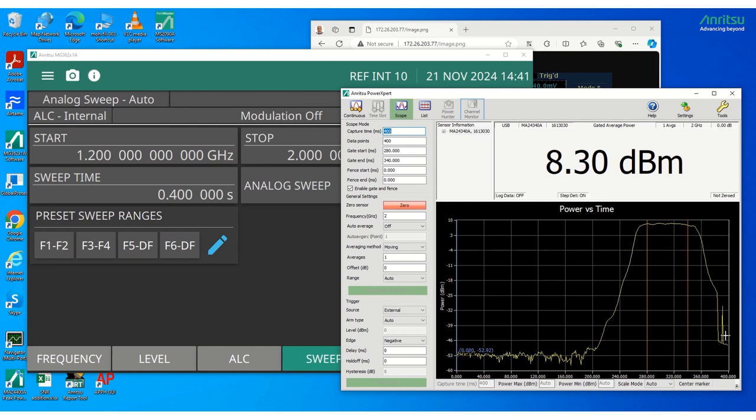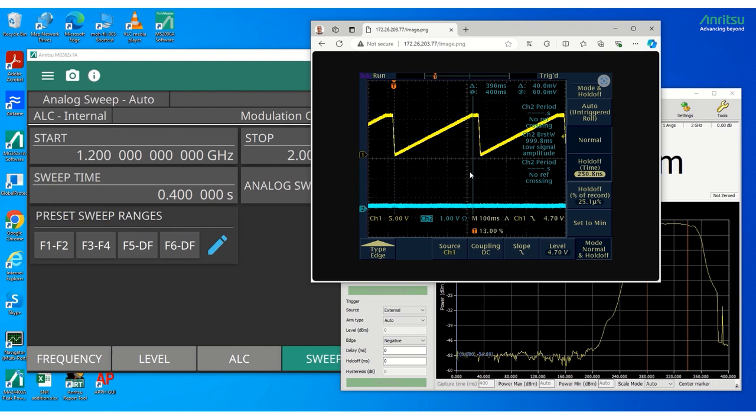Let's look at what is happening here at the higher end of the stop band, and you see a small spike here. So it's showing you a very concentrated RF output power at this point. And if you recall, if you go back to my scope snapshot, I had talked about a brief horizontal period in the sweep signal, which is where the RF output rests a bit before starting its retrace, right?